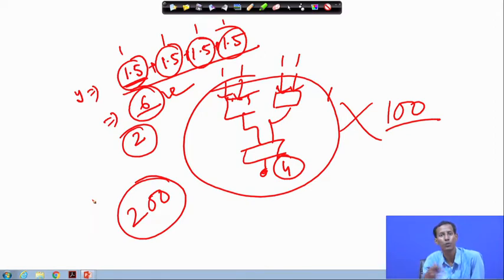Whenever we are doing the algorithmic verification, if we consider only floating point number representation, we will not be that much bothered about this particular error accumulation. But as we are doing this fixed point operation in the hardware circuit, we have to be more cautious about how much error I am accumulating whenever I am doing the corresponding operation, that means the internal circuit of that hardware.